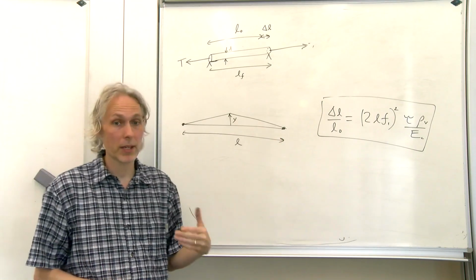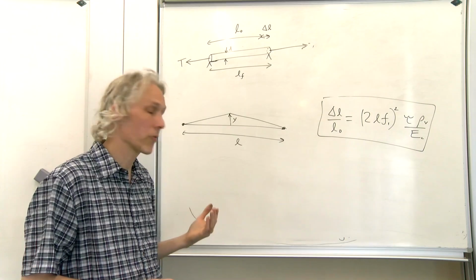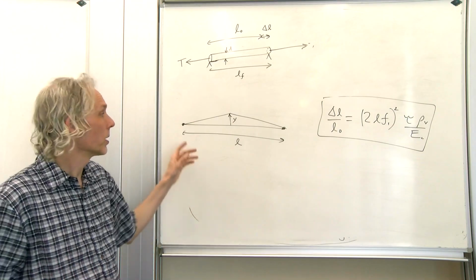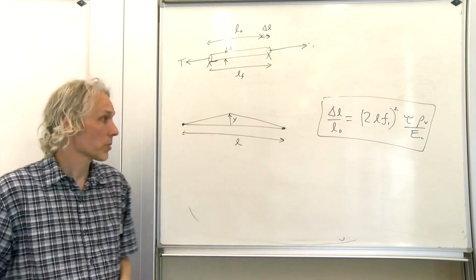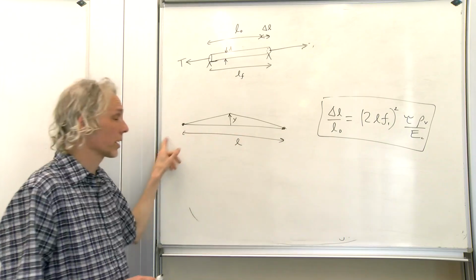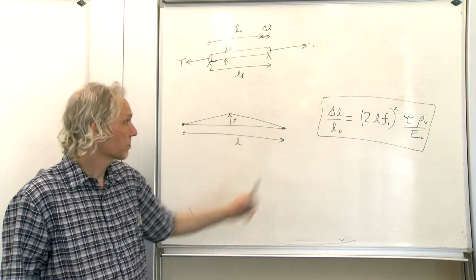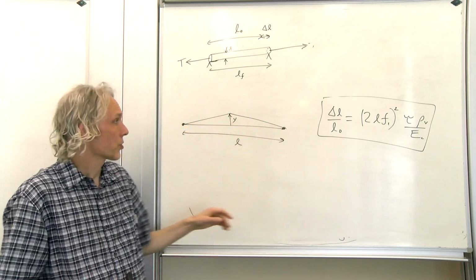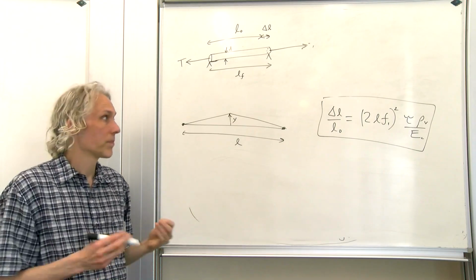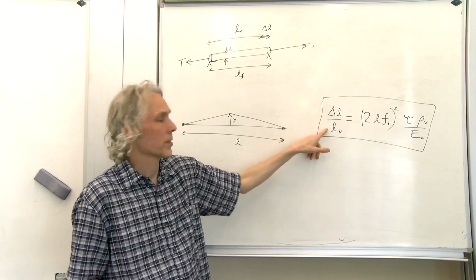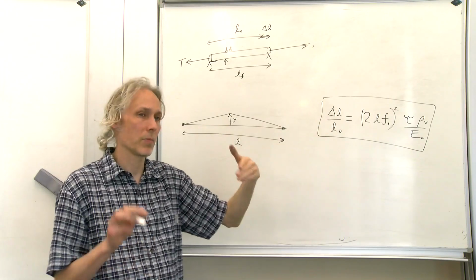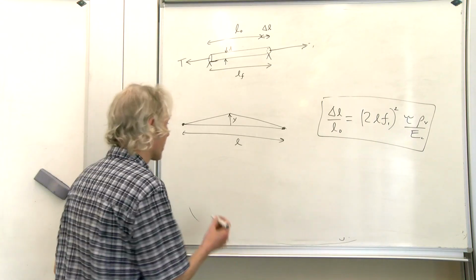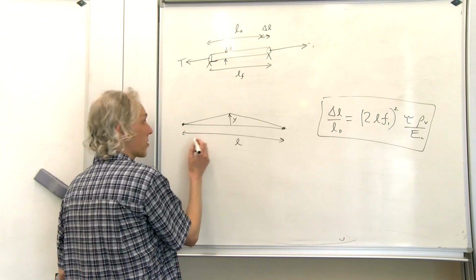They have a small impact that is measurable, and you have to account for it if you want to be really, really accurate. But to give us a general idea of what's going on, we're going to use the first approximation of just ignoring the distances behind the nut and behind the saddle. So L is going to be the length of the string before it was bent. Once it's been bent into this shape, it's going to have extra length, and that's going to add to this number to determine how much the sounding length's been extended. So we're going to check out what's happened to the string in terms of distances.